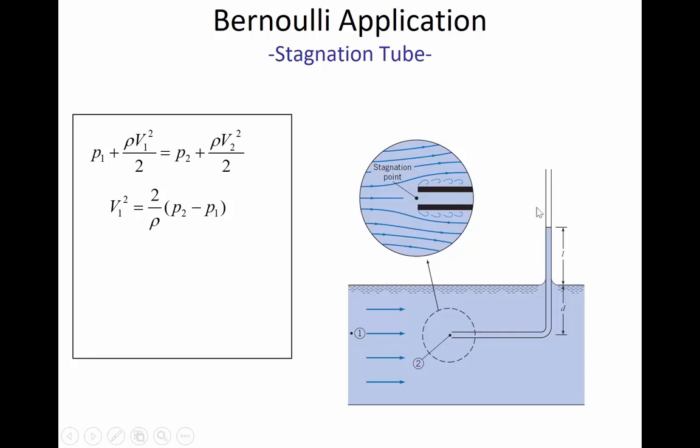The reason the tube has pushed the water up above the free surface that the rest of the water is at, here we can see these little dash marks meant to represent the rippling sheen of water. Well, the water level rose a bit higher inside of that tube that's open to the atmosphere. It's not because there's suction in the tube. This tube is open to the atmosphere, but this rise here, L, is because there's additional pressure at location 2.